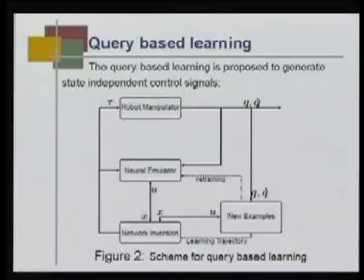So, through network inversion we compute what should be the tau, we actuate that to the actual physical plant, and if we see that the response of the physical plant in the next sampling instant is far away from the value that is set according to the learning trajectory, then we accept that as a new example, because in that zone the neural emulator does not have proper information.